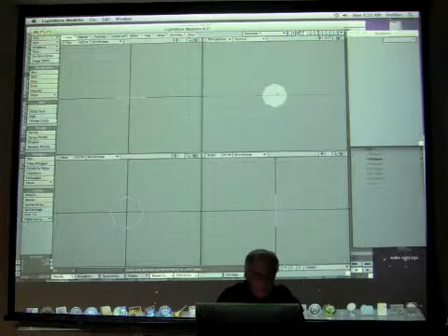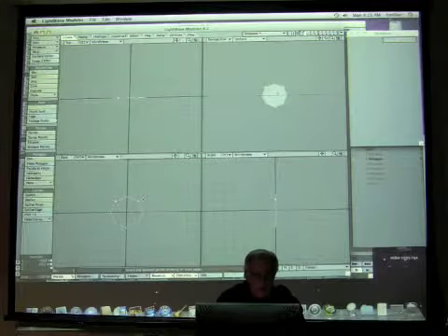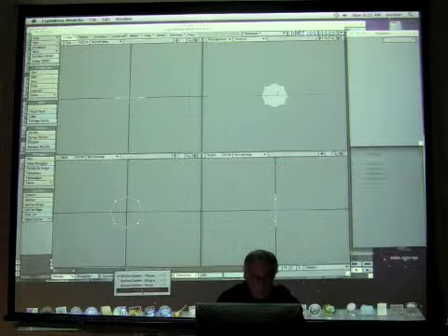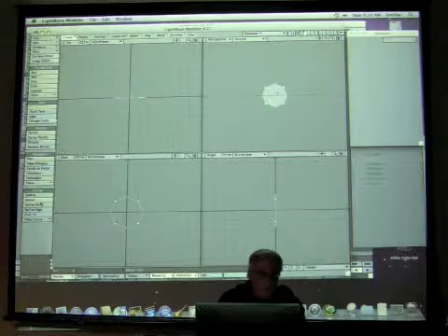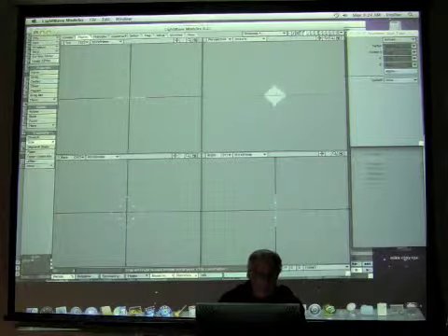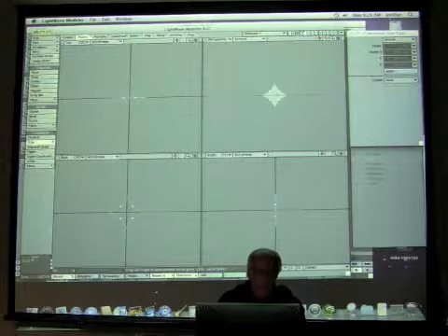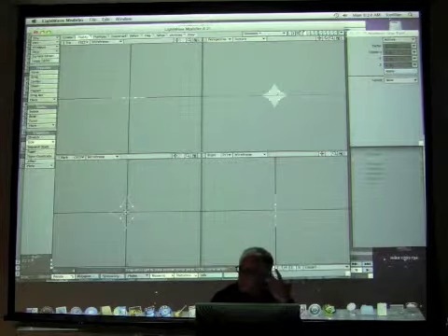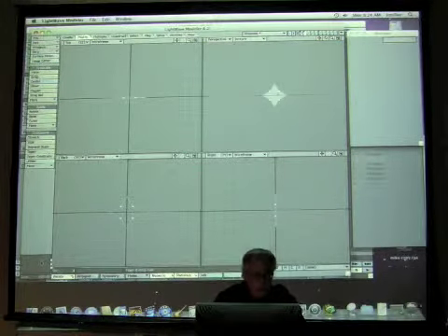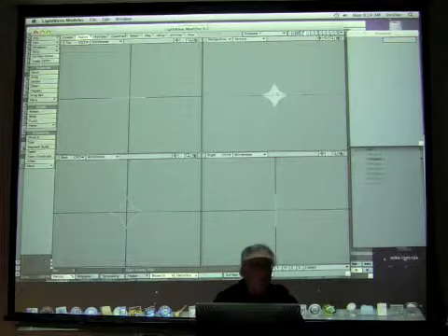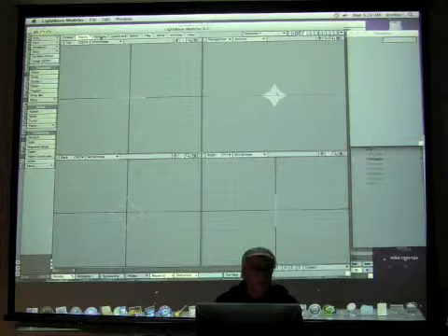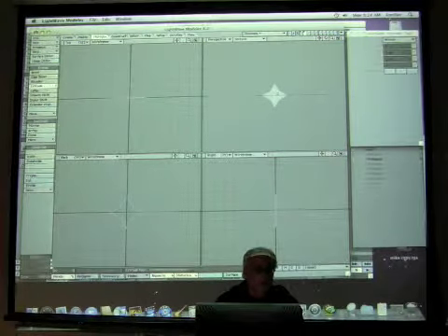And now what I'm going to do with points is select every other point. Make sure its action center is center of selection. What I can do is resize it under modify. And now when I bring it in, see how I get my little star shape? Now start thinking this way. Turn that off, turn the size tool off, deselect. And now I want to turn this into a three-dimensional form. So now I can go back to multiply and we can select extrude.